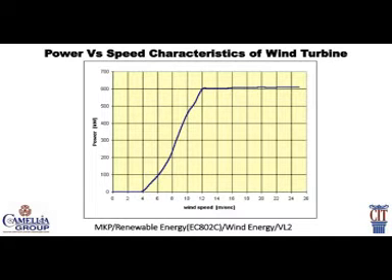If the wind speed is not fluctuating too rapidly, then one may use these wind speed measurements from the anemometer and read the electrical power output from the wind turbine and plot the two values together in a graph like the one you see.